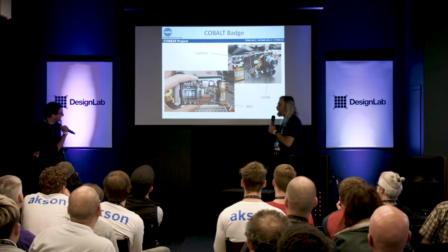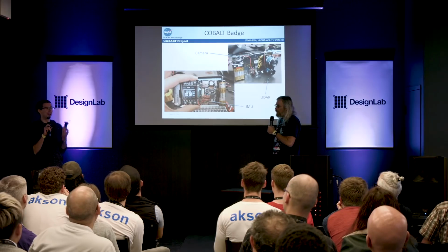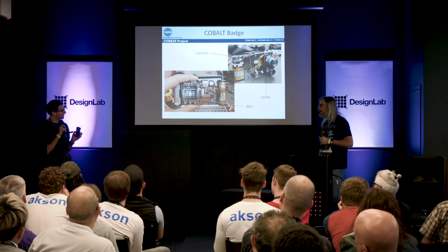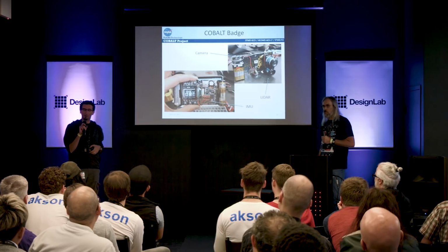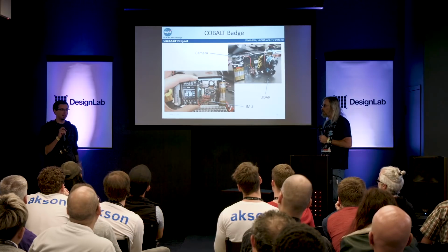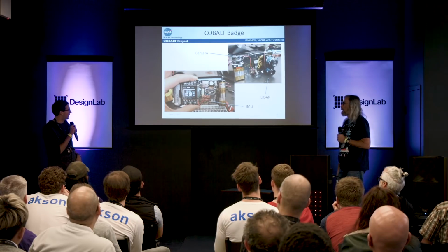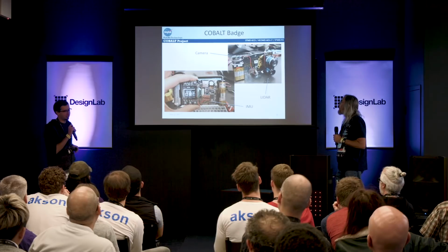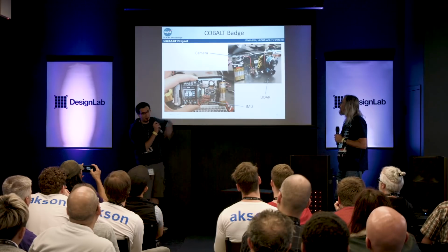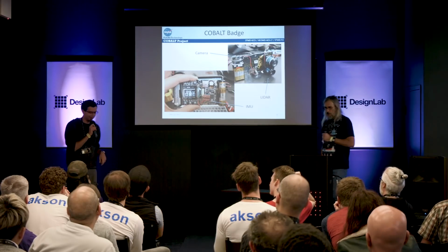Isn't that your Hackaday badge, Arko? It is. So on Friday when I actually got this badge, I was looking at it, I'm like, it has a camera and an IMU, and sure, it's missing a gyroscope, but that's like 2/3 of our payload. And I'm like, man, if I had a LiDAR, and I remembered, I bought one of these off of SparkFun, and it speaks I2C, and there's I2C ports on here, so I integrated that on there and turned it into a very overpriced measuring tape. So you could actually point the camera at the thing you want to measure. There's a little crosshair and then a little readout of how far away that object is. But with enough time and code, you could probably implement Cobalt on here.